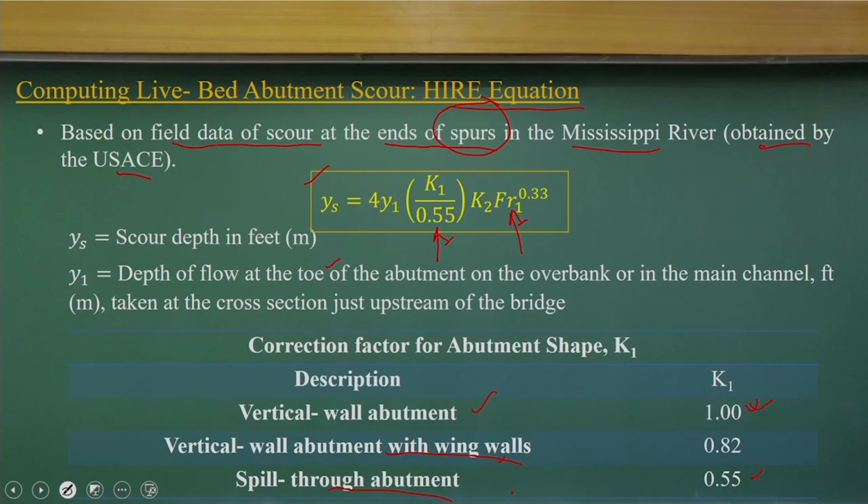That's the engineering skill where we try to understand how K1 and K2 change things, because we know the flow depth, which we cannot change. We know the upstream flow depth for a design flood. What we can change, as hydraulic designers, is the K1 value or the K2 value.